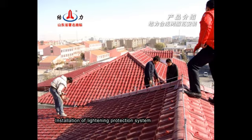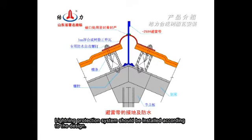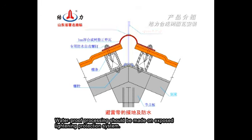Installation of lightning protection system. The lightning protection system should be installed according to the design. The connections should be strong between the lightning protection system and earthing. Waterproof processing should be made on the exposed lightning protection system.